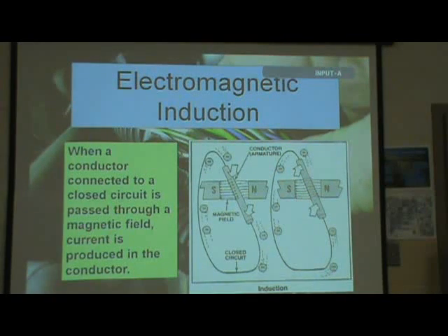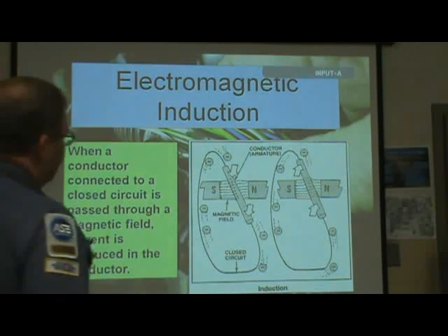Now on your alternator, the stator, look at this thing over here. Can you see this thing on the board? That stator on that alternator has got 3 windings. And if you stretched them out, they're wound one of 2 ways. They're either touching at each corner or they're touching in one spot with 3 ends. Okay, but they're not touching each other, they're only touching in one place. They got them wrapped around, and that rotor in the middle of the alternator is magnetized, and it spins and it creates the power that charges your battery and keeps your car electrically fired up. And they use this induction principle to do that.